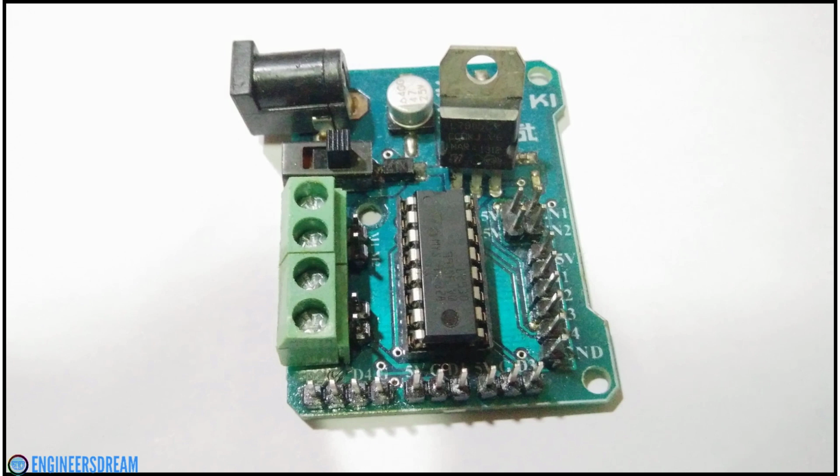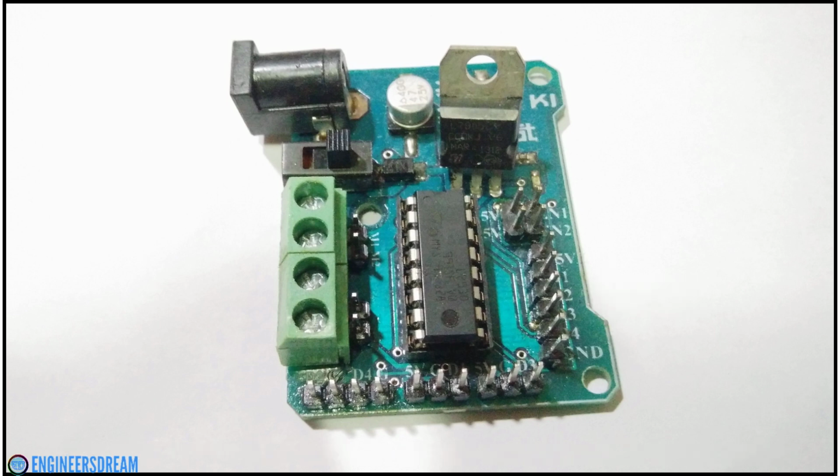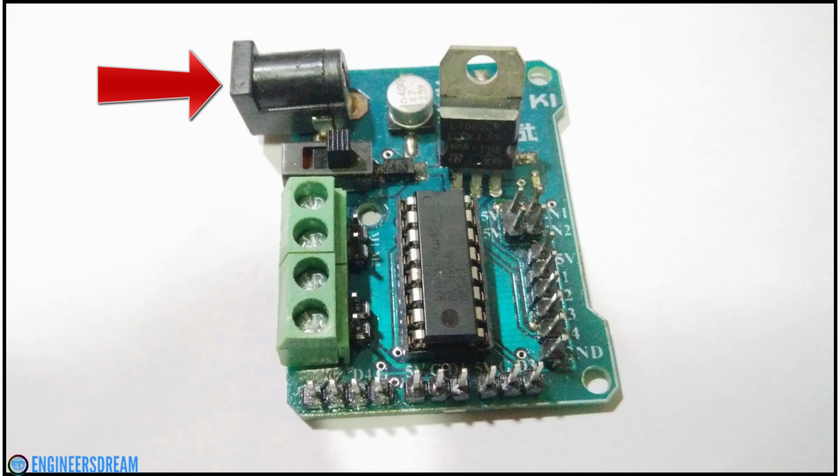And if you look at the last motor driver, then this motor driver is more advanced than the other 2 motor drivers. It consists of D1, D2, D3 and D4 pins, which are connected to the input pins of the L293D IC. And as you would have guessed, these pins will be connected to the Arduino's data pins. The DC motors will be connected to the green sockets, which are labeled as M1, M2, M3 and M4. And I had to connect a battery to the DC jack connector for providing power. The breakout board also consists of an on-off switch, using which I can switch on and switch off this board.